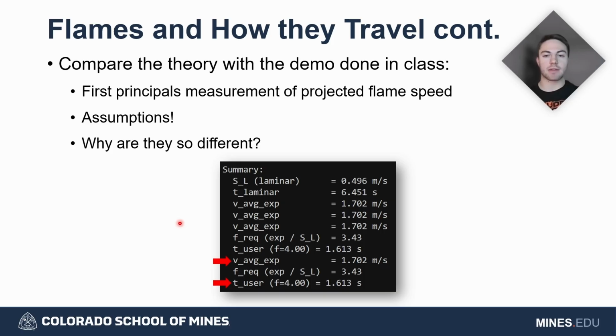So for that, the flame is capped at a maximum speed, and anything above that has to introduce either flow differences, like there's a medium that's flowing through the tube, so the flame speed and medium speed have to be added together, or it can be a turbulent flame. Turbulent flames can move significantly faster than laminar ones. So that is my best guess of what's happening in here.